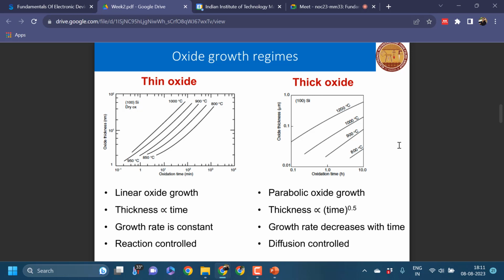Around 100 nanometers. Yeah, for thick oxide, there will be a few hundred nanometers. So a thin oxide will be much less than that, right? In the range of 30s or 50s. So that will be a thin oxide, and the thick oxide will be in a range of 100 to maybe about 500 nanometers or so. Is it right? Yeah. So that's correct.